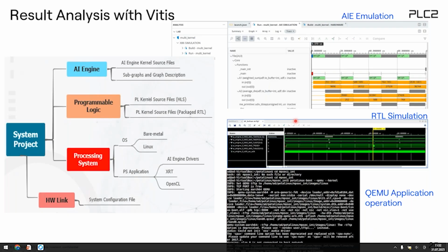So when we look into it, what you see in here, if you do such a complete system simulation, is that you will be able to trace your overall transaction level of the CPUs, like when is this guy requesting a certain memory portion, when is it writing to it. You can see your PL kernels in here as well. That would finally show when they're accessing data, when they are processing, and you would also be able to combine your AI engine level reports in that kind of thing. So what I can see is always a very distinct time trace, for example, of all of the different contributing partners. And in the same way I can have correctness checks and printouts from my PS software.